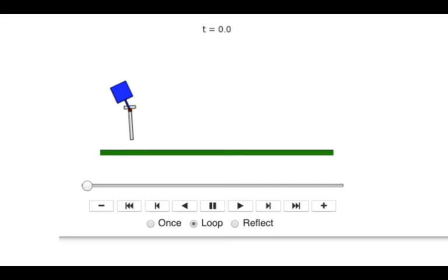The other problem I investigated was an optimal fast gait for the hopper. To find this, I added a cost term which penalized low initial speeds, while removing the position constraint on the final state. The nonlinear solver was able to find a solution that covered nearly 7 meters in one hop.